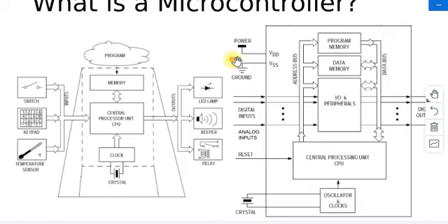In other systems also, some push-pull amplifiers are required, and similarly for increased current, a Darlington pair transistor is required to provide the additional current, because regarding the sourcing and sinking power, the microcontroller sources less current and sinks less current, though the sinking current is greater than the delivered current, meaning it provides a small amount of current, near about milliamperes.